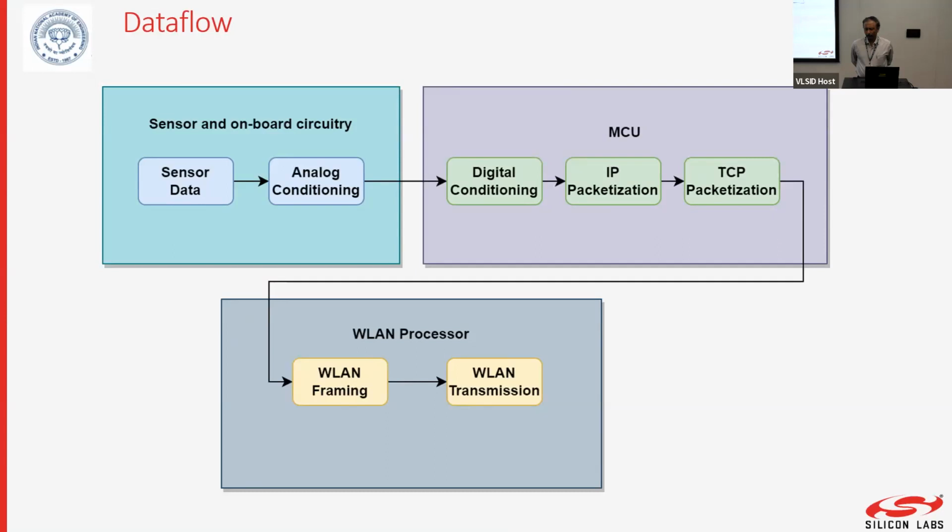When a wireless transmission happens, the battery type determines the peak current that you can consume. Wi-Fi consumes a peak current of maybe 200 milliamps. Original Bluetooth consumed maybe about 40, 50 milliamps. They found that you cannot make an ultra small device with a coin cell battery unless you do something about it. So Bluetooth Low Energy came with a better and more efficient modulation scheme called Gaussian MSK, where you could have 15 milliamps of peak current, and then you could suddenly use a coin cell.